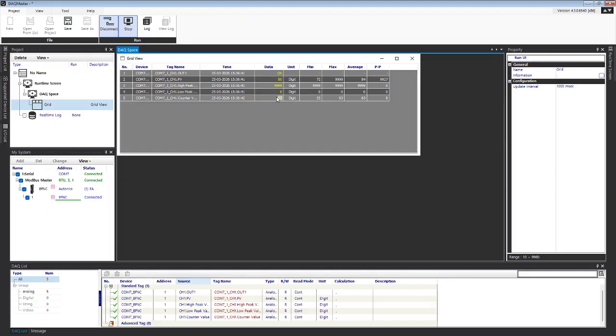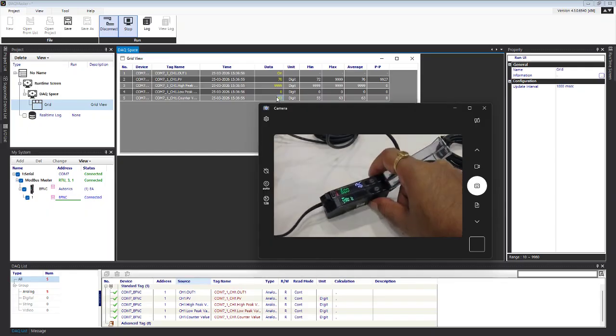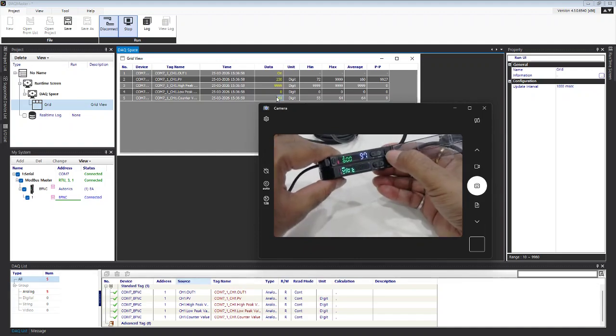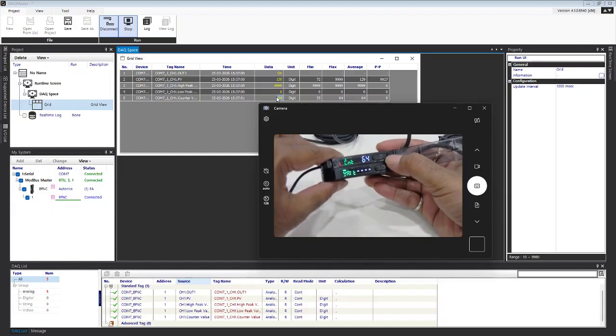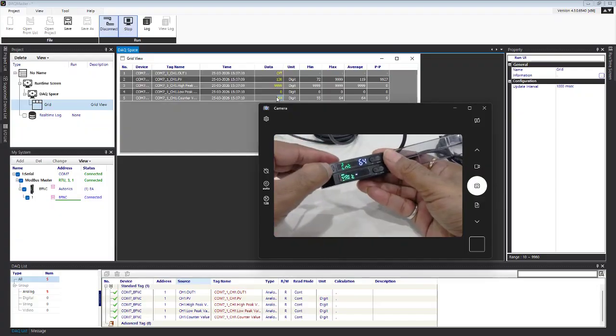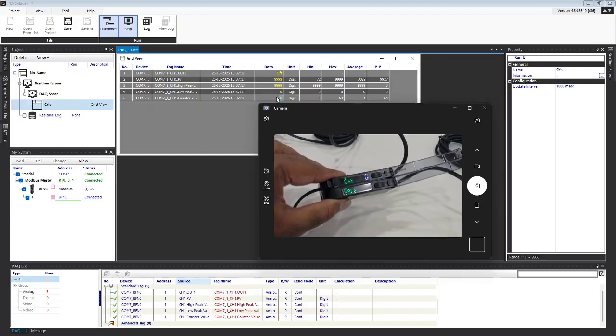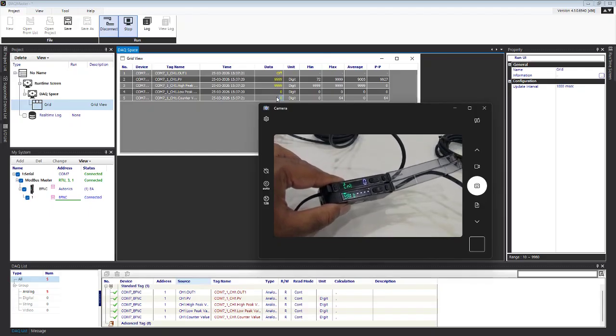Yeah, there is no register over here through which we can reset these values from Modscan. If you want to reset the value, here also you can see we'll find that value in the CNT online parameter. If you want to reset it, you need to press the set button momentarily. Okay, so the reset has to be compulsorily done from the set button. We cannot do it from Modbus or any input.